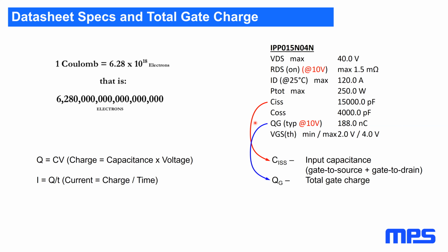Now in reality, you're going to need less than that because gate drive ICs can't source infinite current. So the reality is there's two ways to do it. If you have a good simulation model of your gate drive, you can go with that. What I usually tell people is start with that and test it. Put a resistor in, measure rise and fall times, and then adjust it from there.